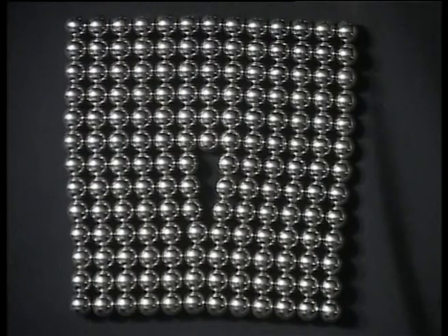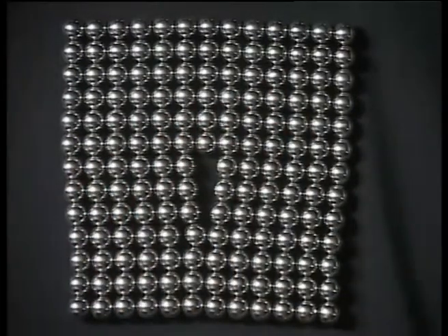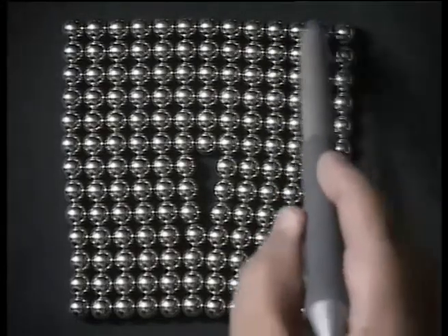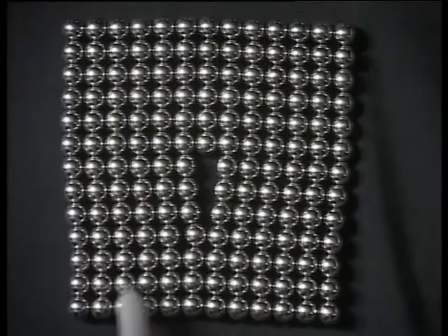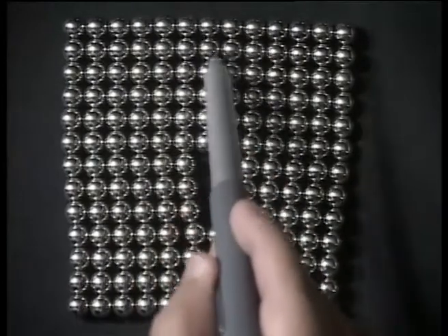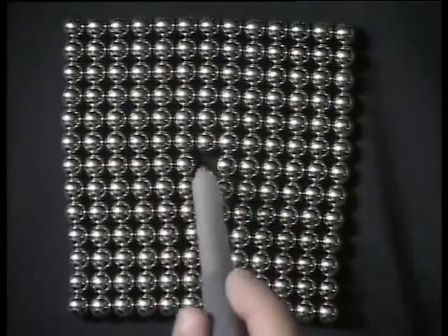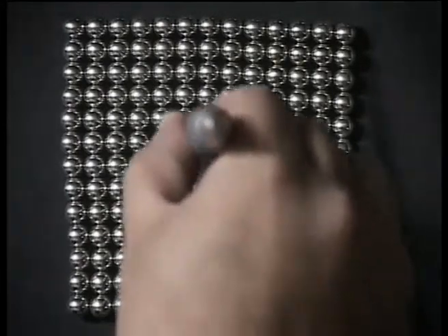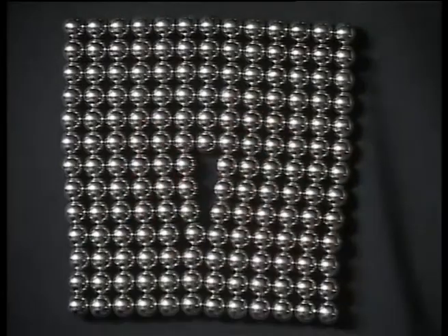The third model I am going to show you, perhaps a little ahead, and we will come back to this later during the course of this lecture, is again a ball model in which I am showing a dislocation. This is of course a very crude model, not a realistic model of a dislocation, but nevertheless you can see that the crystal, if you look at this corner, looks perfect. The crystal here perhaps looks perfect downwards, but here there is an extra half plane of atoms, or you can otherwise think of it as a missing half plane of atoms at the bottom. Somewhere here, along this middle line where the pen is, I can visualize a dislocation line.